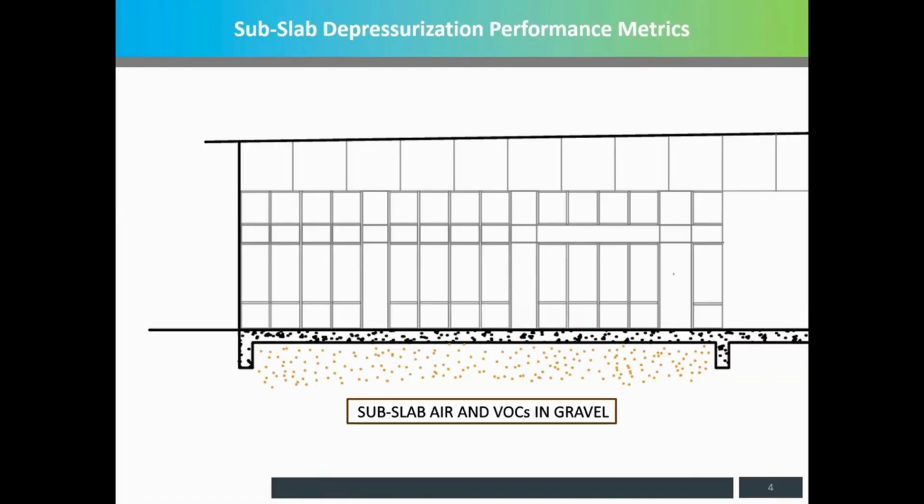And then there's diffusive flux, the transport of VOCs down a concentration gradient. In an environment of high concentration of a compound, and that's these orange dots you see below the slab, diffusion causes the compound to move into areas of lower concentration. And that's the other dots you now see above the slab. Diffusive transport occurs independent of pressure gradients or the net movement of matter. Michael Nemeth will elaborate on how that works in concrete, also later today.